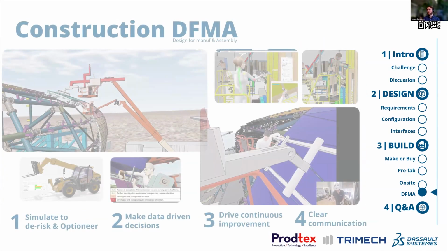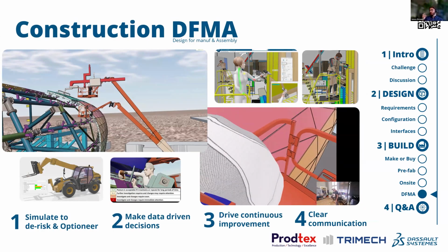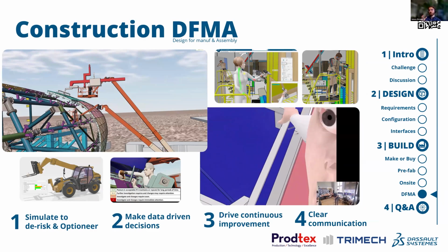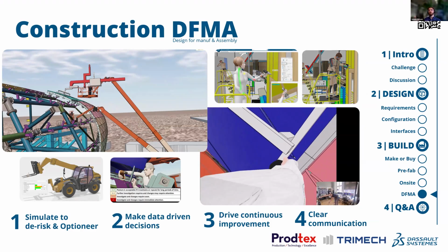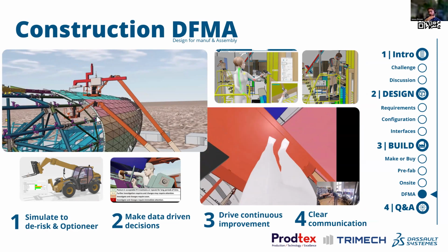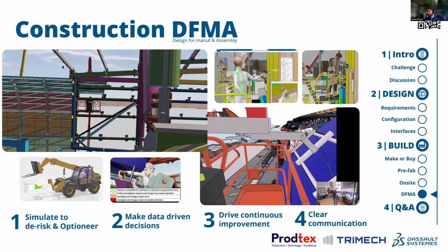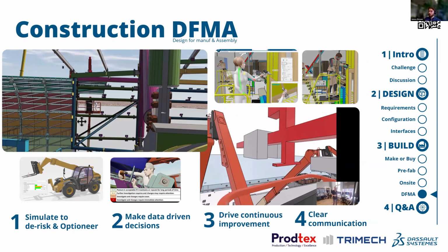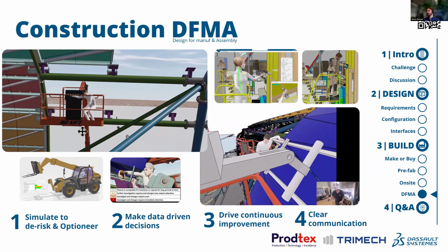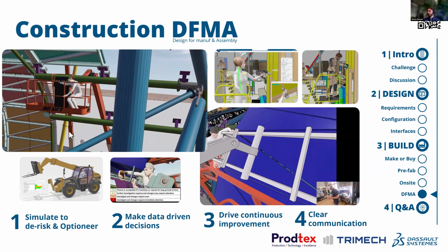Cool. And then my last slide, pleased to know, was really just touching on that DFMA point again. So I mentioned a second ago, I've got some things on site here. This is actually the Everton Stadium in Liverpool, where we were looking at that facade panel. So doing this for real now, how are we actually installing that? First, understand the processes. What's the bolts? How are we getting there? What do we think is going to happen? We then simulate it to say, can we actually do that job? And then off those simulations, we could see if this thing can reach or not reach.